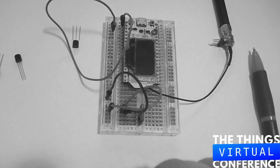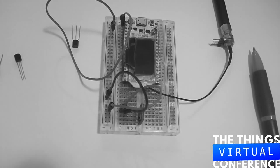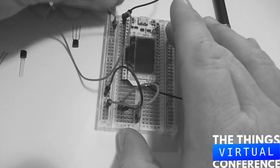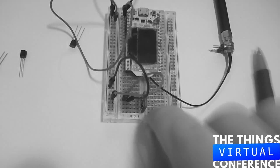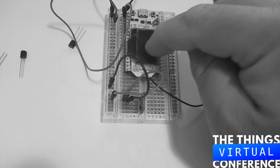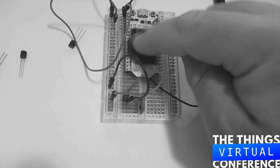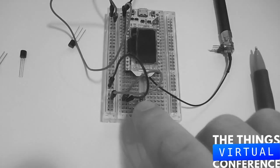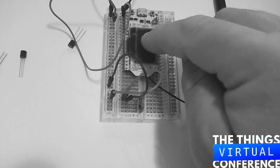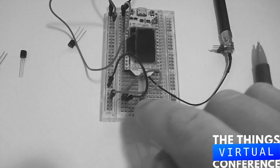And then you would connect it to the ground of the microcontroller. And that is maybe number 1 up here. And let's do the second. You have something like this. And then you would find the pin out for the microcontroller development board, and you would find the SDA line for the I2C and the SCL or clock line for this communication standard.